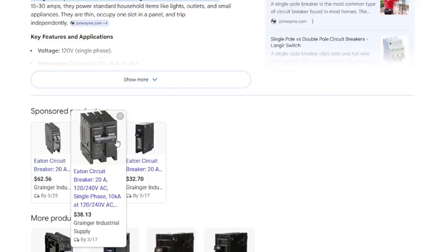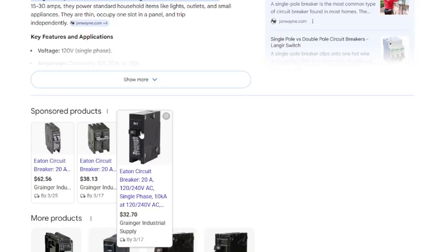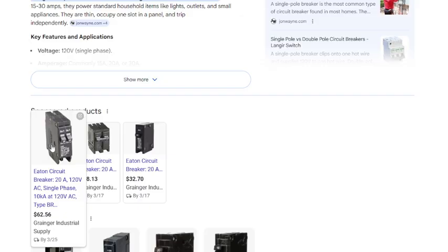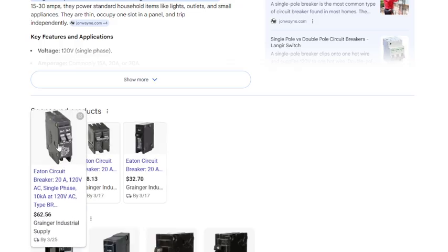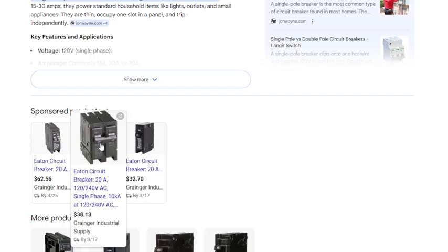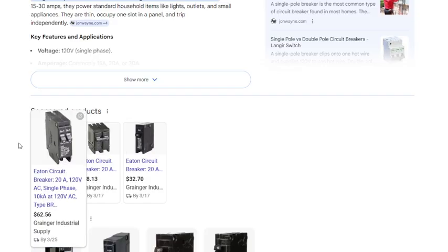This one already has the bar. 2 pole breakers come with it. Or use 2 of these side by side, and again, they do sell a bar to join 2 of these together. But you're going to take up a lot more space that way than if you use one of these, right? Because these count for 2 of those. So now you have 2 of these taking up 2 big spaces in the panel, where you can use one of these. And now again, you can put a little bar between both of those, just the same way that one is set up, and shut them both off at the same time.